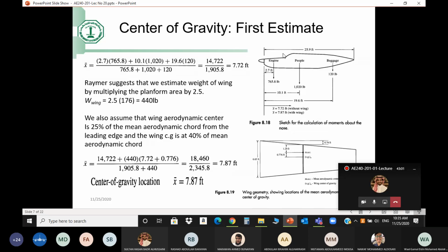What you can do is to have this drawing not with 3 parts, but with 4. Draw the wing here and you're going to have a force: 1, 2, 3, 4. For each one of them, you have a weight and you have an arm. Here is the weight of the wing and here is the arm. And that will give you the total CG location, including the wing. I hope you will be able to do this for your aircraft because you have all components as well.